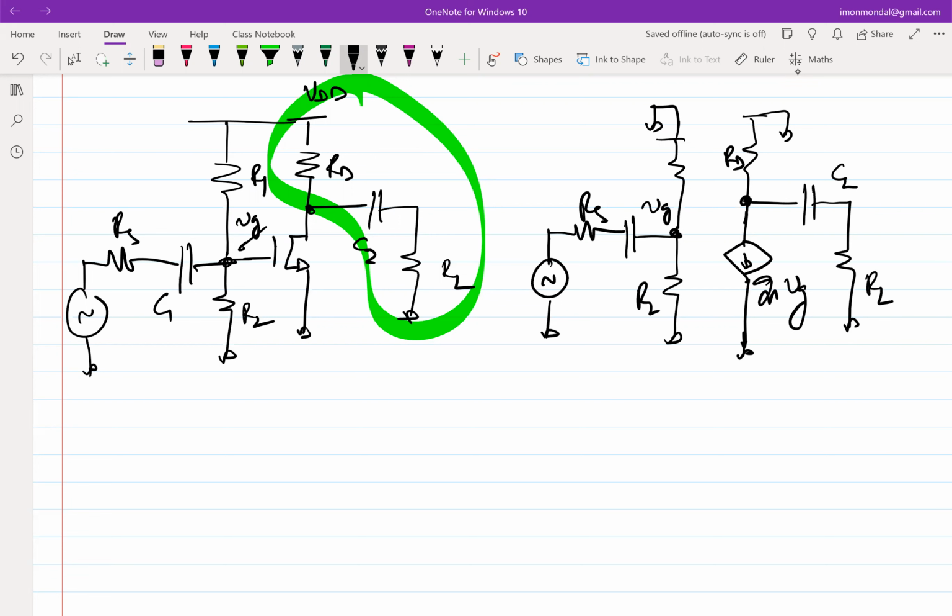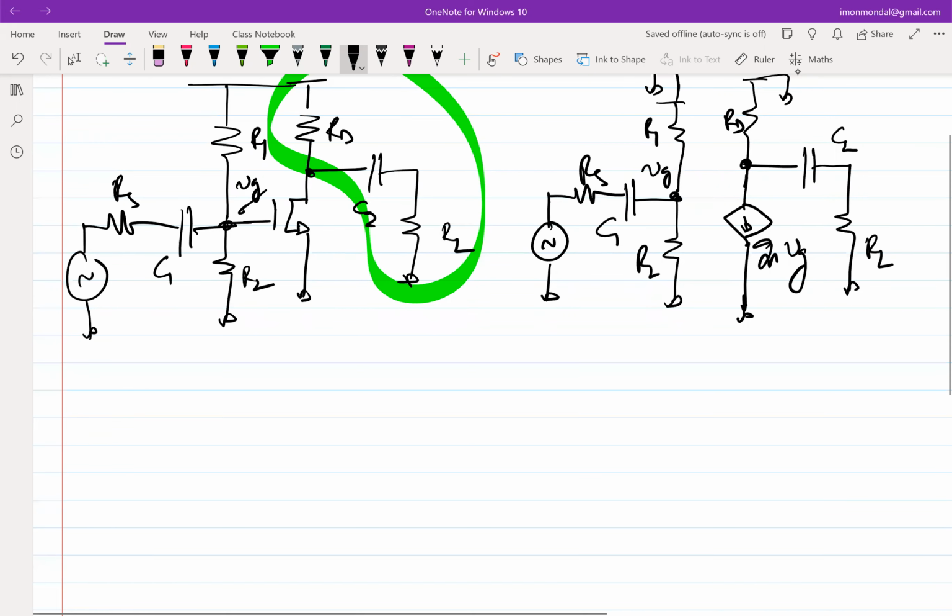In the part on the left, if the capacitor has to be sufficiently large, a certain condition needs to be satisfied. Ideally, I want C1 and C2 to be large enough so that they are shorted at the signal frequencies. If that assertion has to be satisfied, what am I essentially saying? The voltage drop across C1 has to be much lesser than the drop that I'm having anywhere in the loop. So what does a short essentially mean?